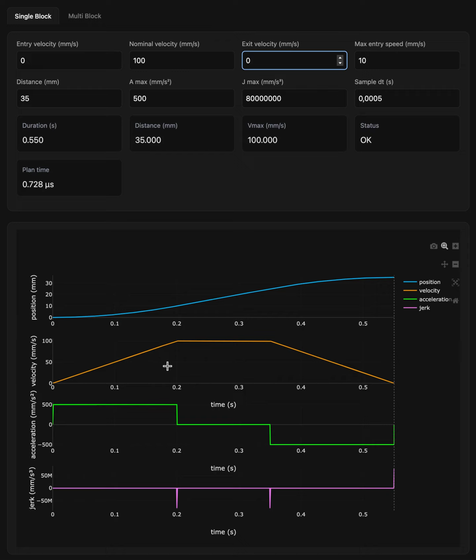And the universe really does not like discontinuous velocity, so it does not like things changing speed instantly. That's why the original linear advance implementation used to limit acceleration, so that this discontinuity was bound. It was small enough that the extruder would cope anyway.